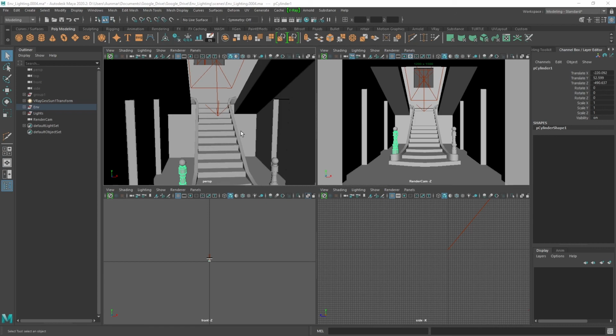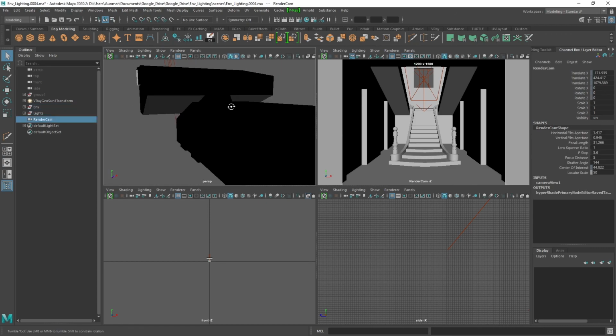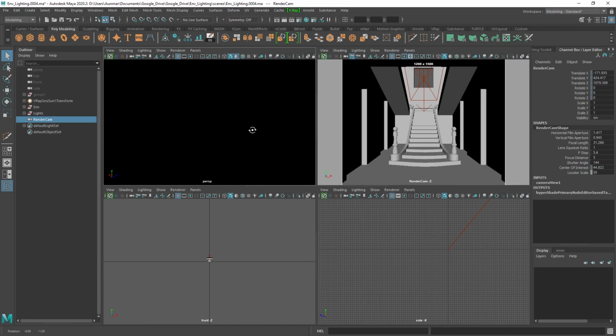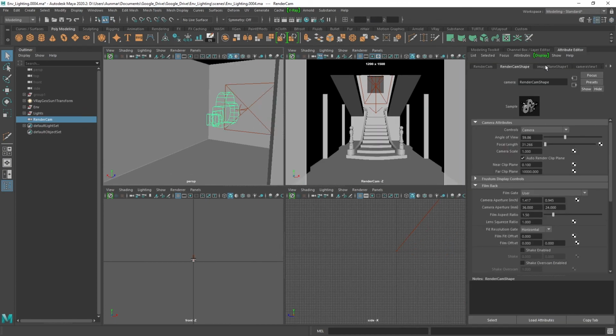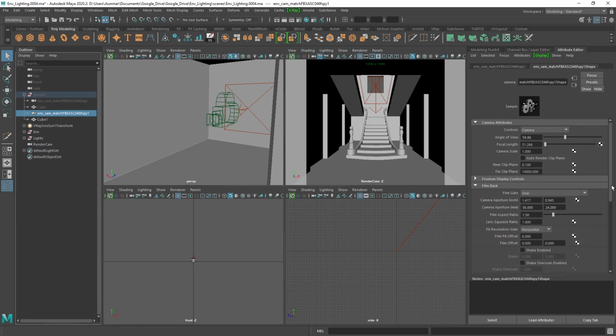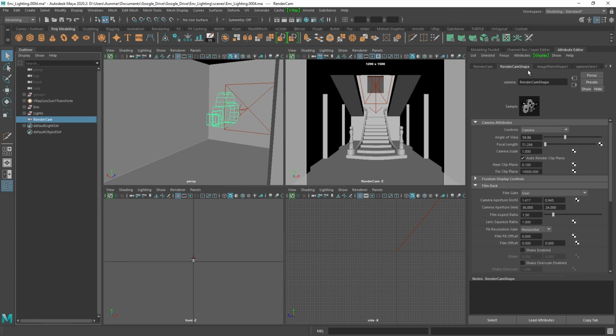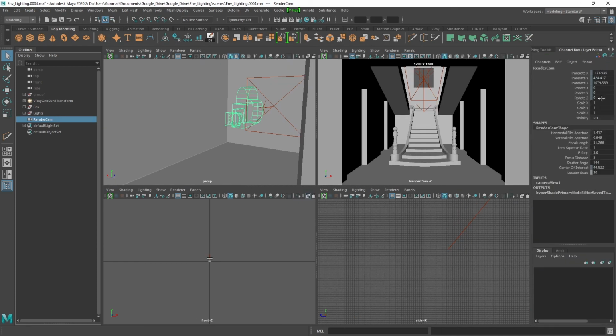The last thing I wanted to add was that when I started setting up the camera for this, I did have to recreate the camera and then reapply all of the camera positioning and settings from the import that I brought in from Blender and fSpy. For whatever reason, Maya did not like me putting the V-Ray physical camera properties on the imported camera. So all I did was copy over all the transforms and the settings for the focal length, and then we were good to go. Just a little bit of a hiccup there, but after that, we were all set.